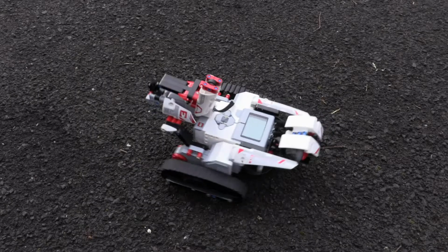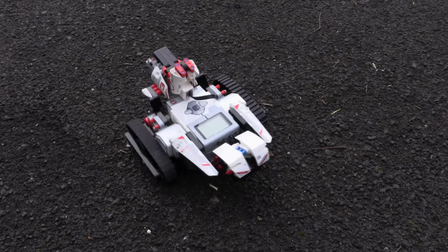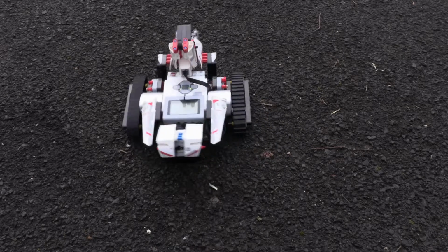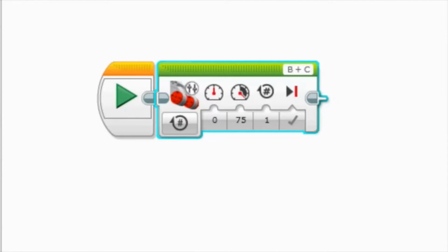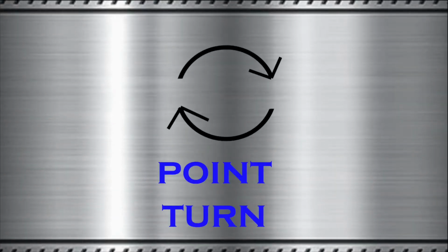Much like when a tank turns, it uses only one set of caterpillar tracks, generating this swing effect as the moving caterpillar track runs a circle around the stationary one. If you swap the option settings around and set the left power option to 75 and the right power option to 0, then Eve will turn in the opposite direction, to the right. Simple as that.